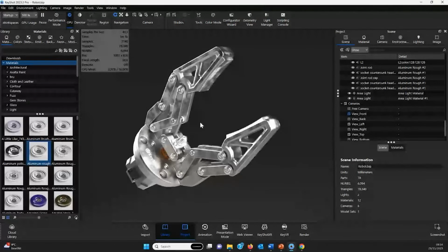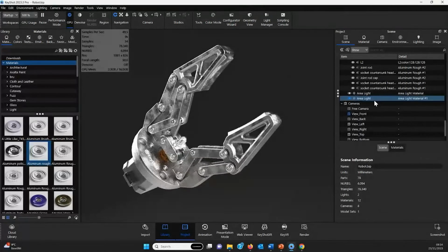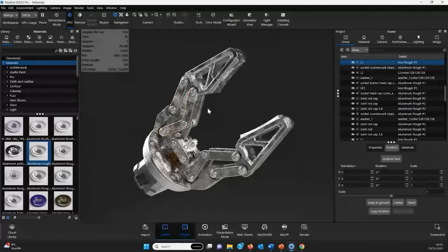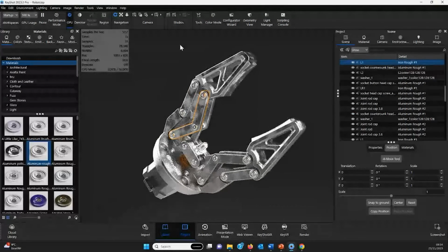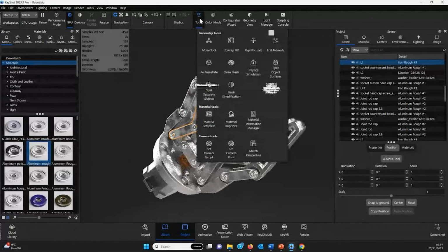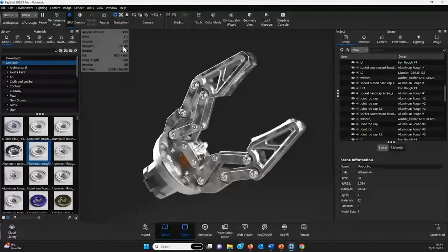So for example, you can select one geometry where you want to change the tessellation, switch to the tools, and you can work with the retessellation tool. So if you notice that you still have too many triangles in your scene, you can still reduce the triangle count after importing it with 0.001. Yeah, perfect.